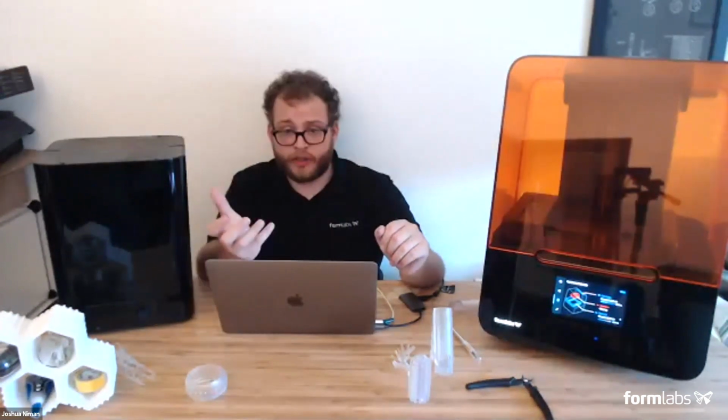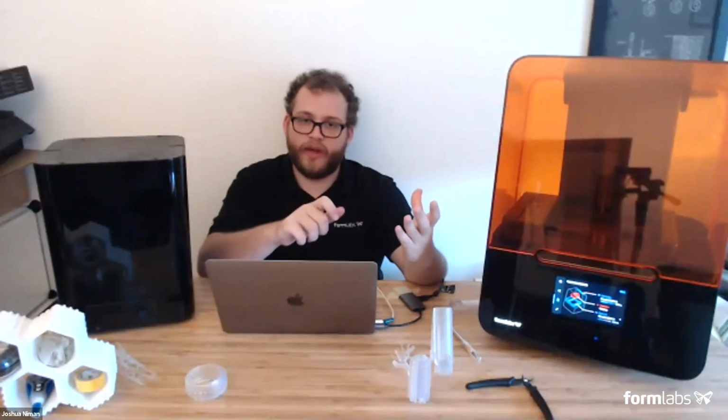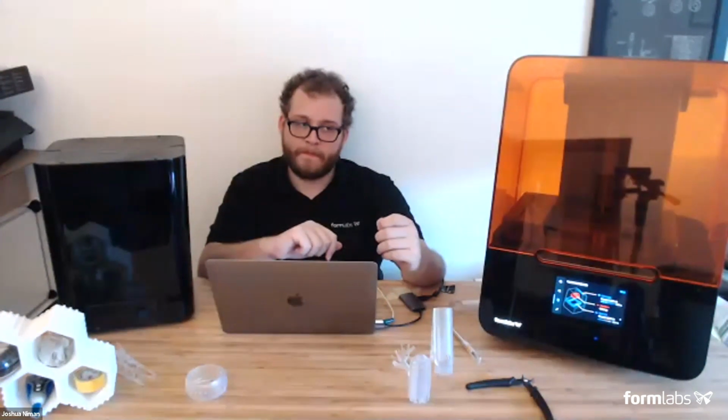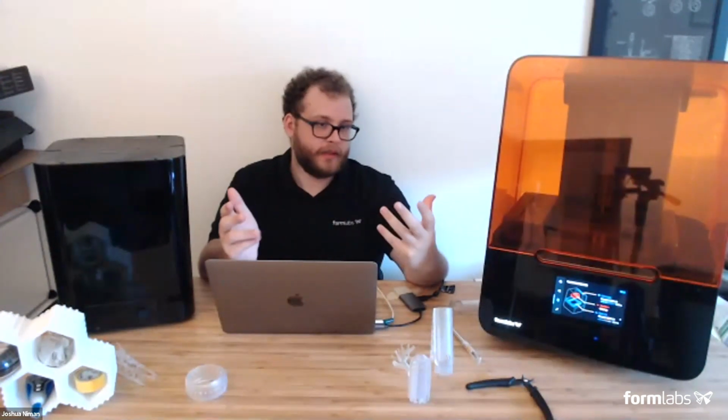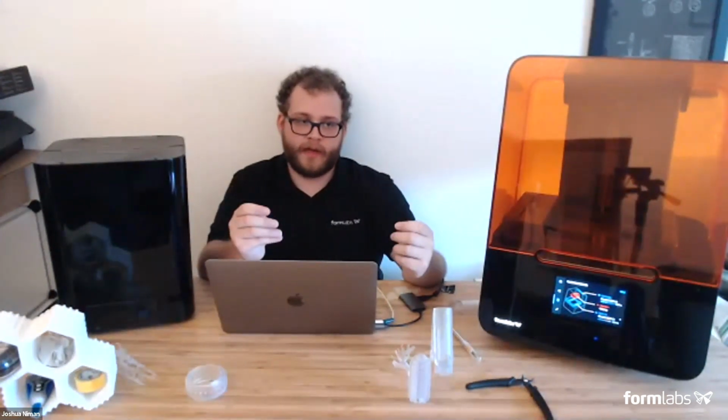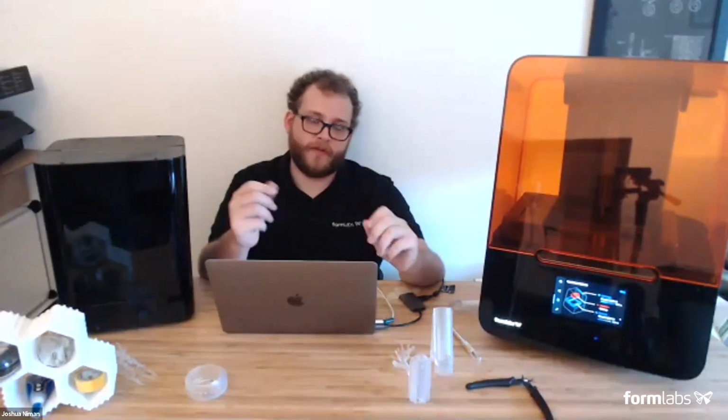So I will generally take a squeeze bottle, fill it with IPA, and in a safe, well-ventilated space, over the Finish Kit, blast it down with IPA. I think the stickiness is just a function of it being a pretty viscous material, where the liquid material hangs around the part and it's hard to wash off. That more aggressive washing always solves it for me.